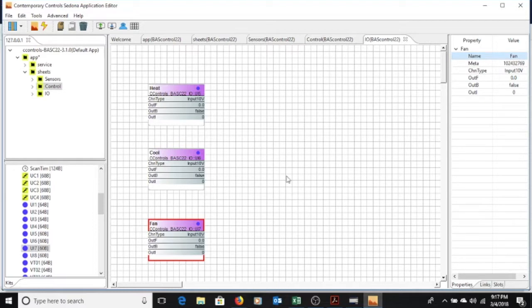Now that we have our inputs, this will be from your switch box that you were given at the event. You have heating, cooling, and fan. If you notice, on every single thermostat in the world, there is heat, cool, and fan, right? And also, obviously a way to change your set point up, change your set point down. Now, fan's fairly simple. Fan would go out to obviously an output.